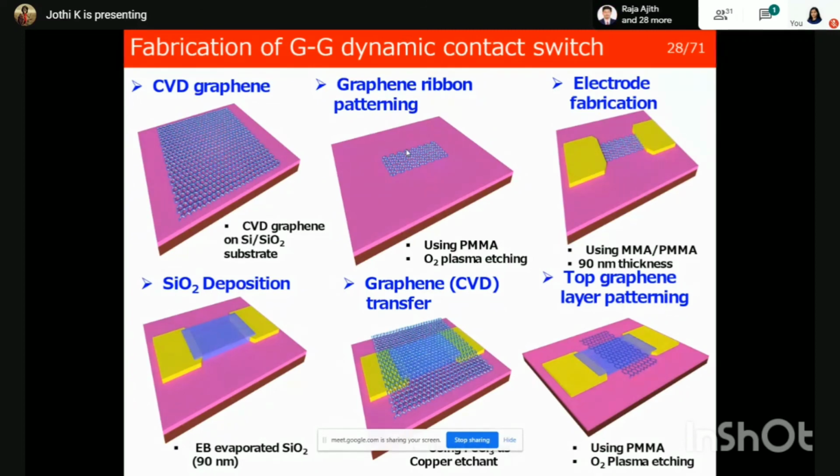as you can see here, this part is suspended. This means that you can remove the oxide from there. We involve a process called buffered hydrofluoric acid etching. This is one of the very important processes. Once you do that, the chromium normally gets oxidized into chromium oxide.